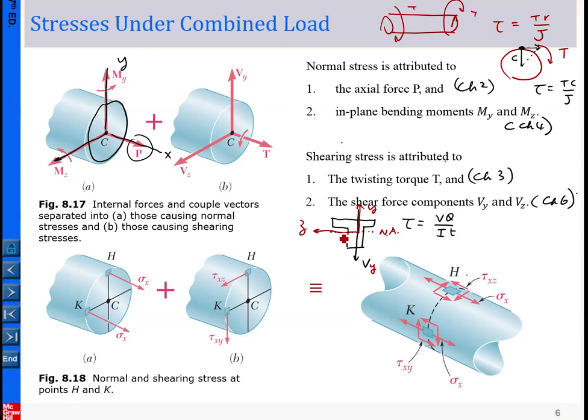Okay, so for this case, V equals our Vy given here, and I is the moment of inertia of the cross section with respect to the neutral axis, which is the z-axis. Okay, so I use Iz. And T, now we're coming to say here, if you are interested in finding, say, the stress along this cut here, then you can pick the shaded area, say like this, and you can determine the Q. Then T simply is the width of the cut measured from here to here. So the width simply is the dimension measured from here to here. So that comes to the T.